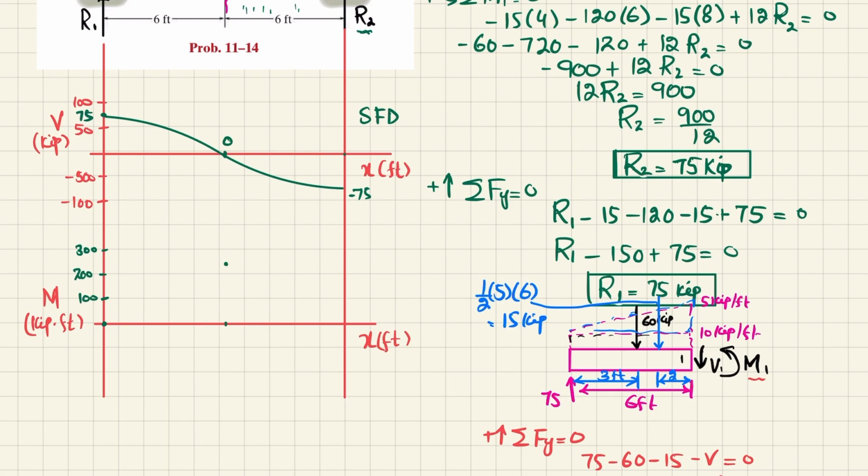Now you can see that shear force is a 2nd degree line. So bending moment will be 1 degree higher and it will be third degree and slope will be increasing. And then, using symmetry, it will go down. So this is your bending moment diagram. So here the moment is 240.